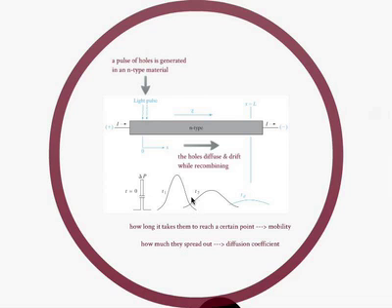Of course, it will diffuse, meaning it will move according to the concentration gradient, which is what we saw before, that it will spread, basically. That's diffusion. But it'll also move, as shown here. So you have a spread here, but it's shifted over. You'll have another spread here, shifted over, another spread here. It'll move because of drift. The holes will move along the electric field. So you see the picture of what's happening? Of course, there's recombination also. So we have many things going on here.